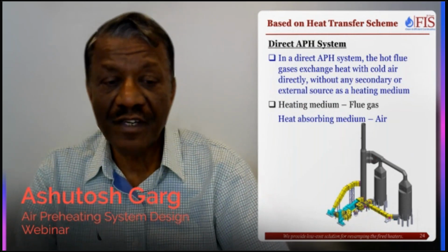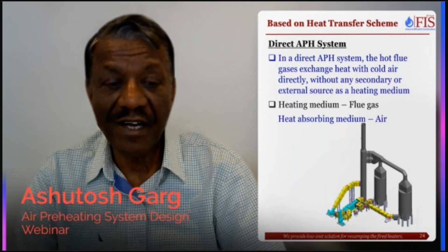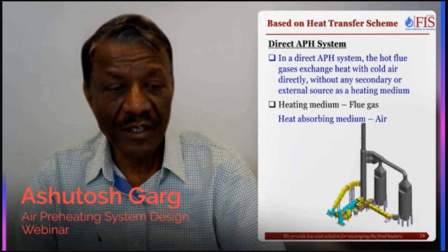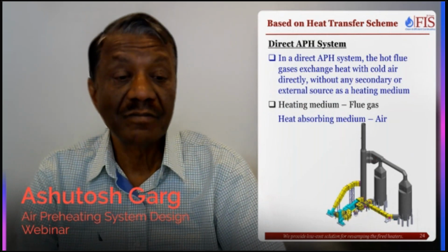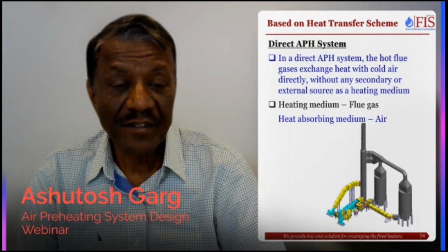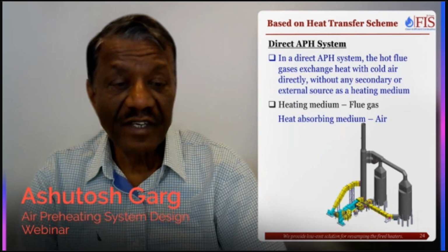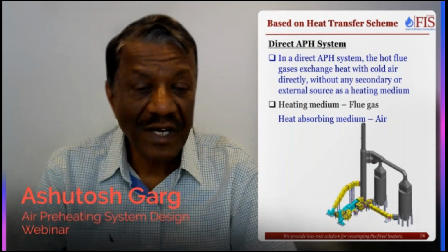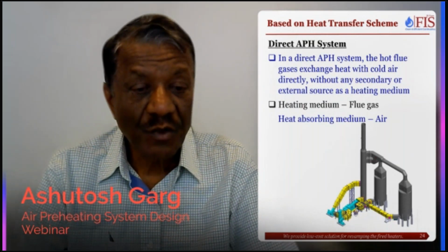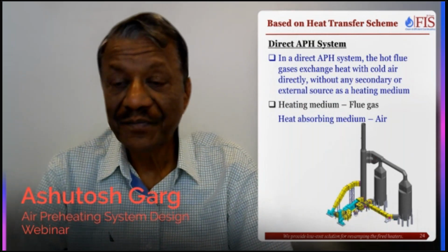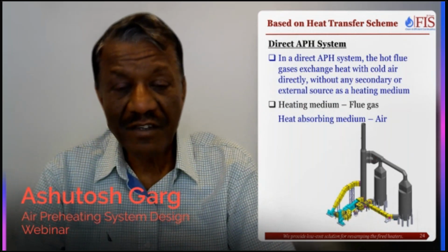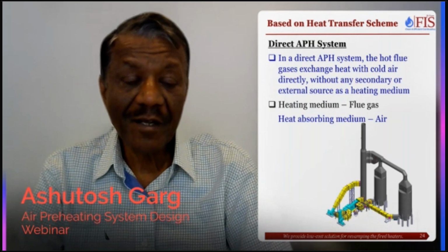Here is the picture of an air preheating system we revamped for a client in Texas. They had two heaters and they had a common air preheating system. And this is a very unique installation. This heater used to have a rotary air preheater, and we replaced the rotary, because the rotary was having problems, with a plate type air preheater.